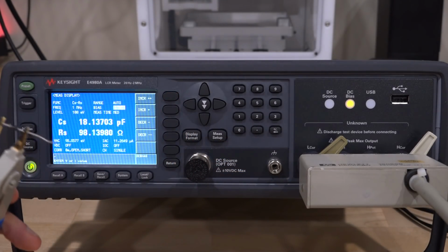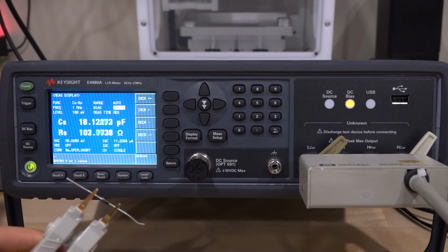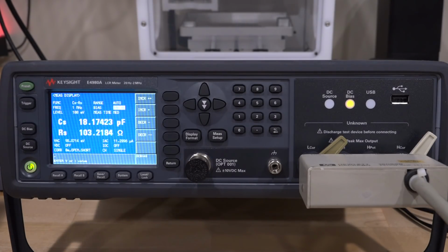So this is of course a varactor. It's a PN junction varactor, and we went from near being forward biased to completely reverse biased. And it's one of the fundamental voltage controlled capacitors that you can build, and it's very common in a lot of oscillators.